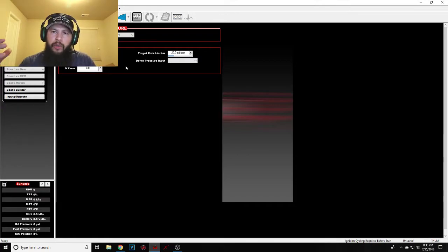If you run into a scenario where you're constantly overshooting or undershooting, these are going to be the terms that you might have to play with to get boost control to be tamed down a little bit. Or if it's too slow coming up, usually it's a matter of overshooting. And these terms can help out quite a bit with that. So can this. So this is a really easy thing to get.